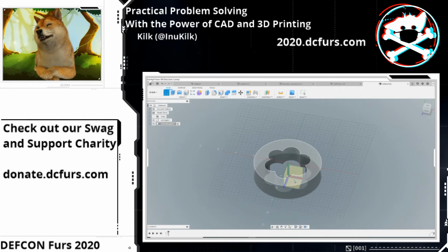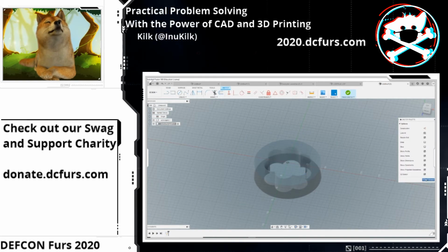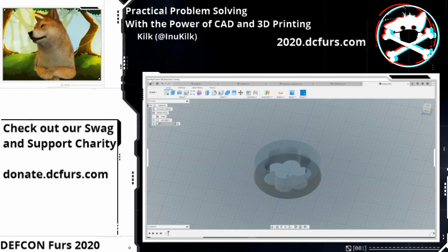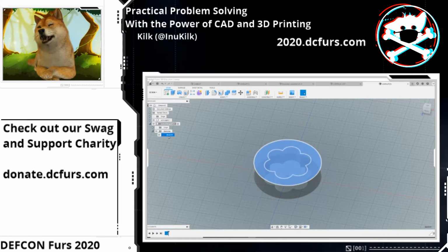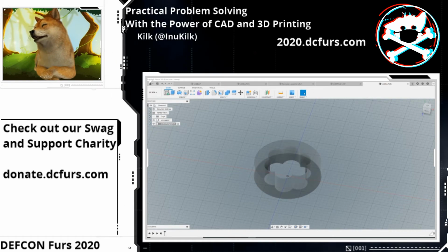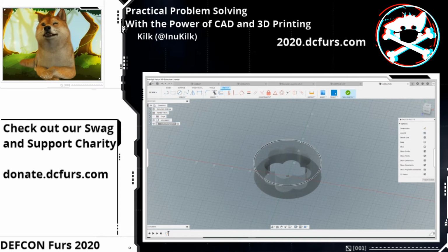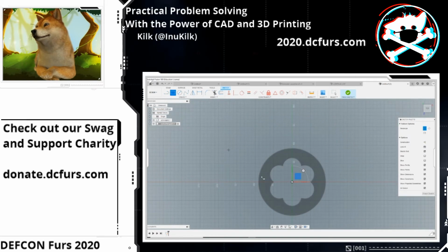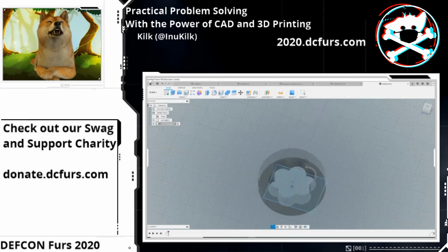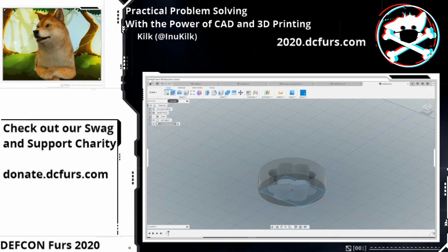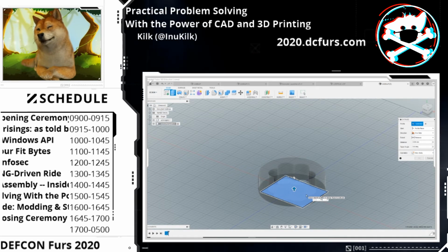We're gonna create a sketch on top of it. Which face did it just try doing a sketch on? Let's just delete that sketch. Let's just create a new sketch on the top plane. Let's do top. Let's create a box. All right, finish sketch. We're gonna extrude it and make it 45.